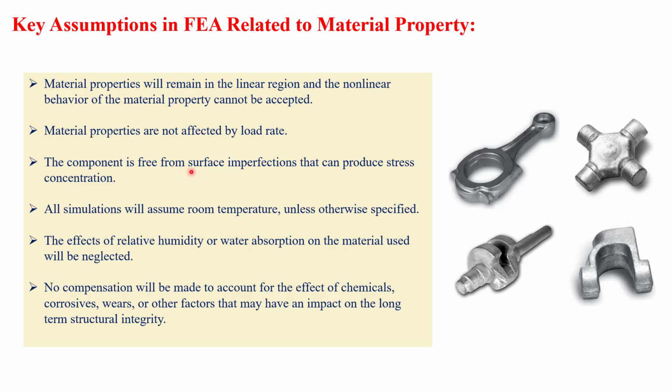The component is free from surface imperfections that can produce stress concentrations. So if you have surface imperfections, we should not consider that. All the simulations will assume room temperature unless otherwise specified. Most of the analysis, 99.9% of analyses, is under room temperature. We don't define any temperature for this. The effect of relative humidity and water absorption on the material used will be neglected. We won't consider that at all in the simulation. In short, we just consider the normal room temperature and start working on the static analysis.